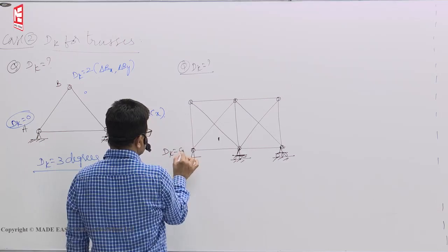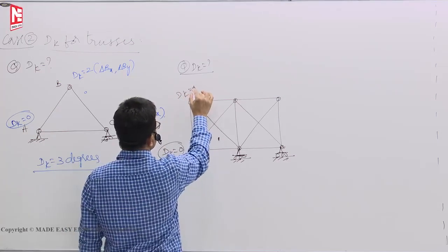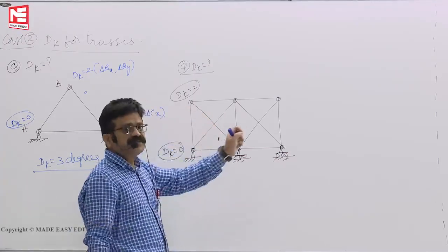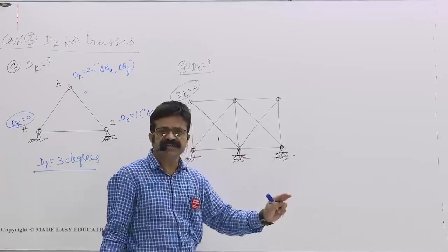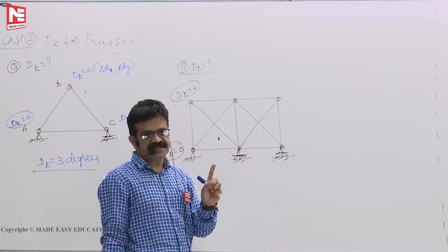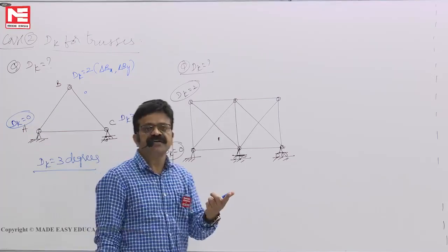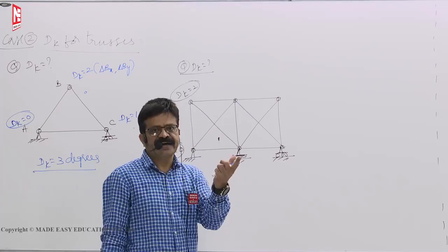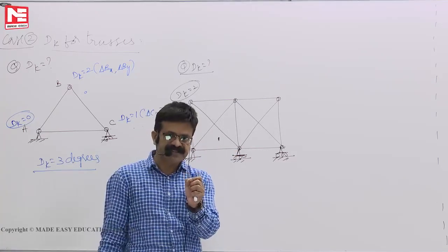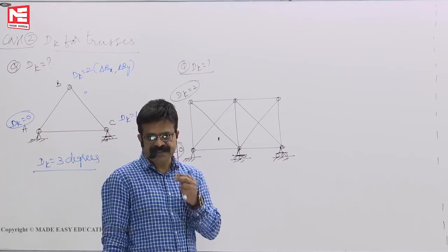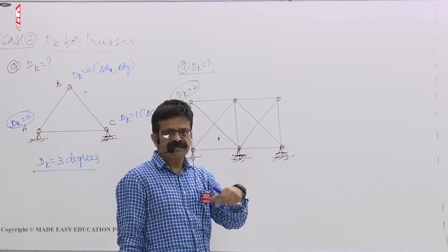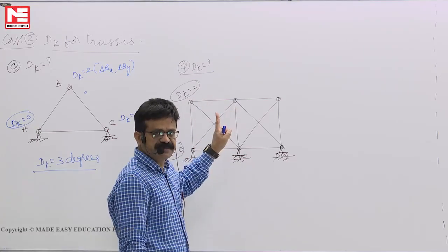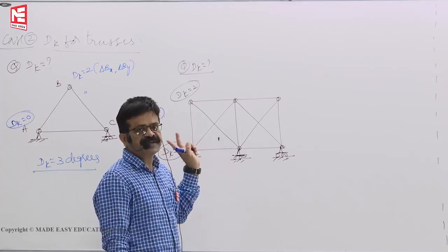Here dk is 0 because it is a hinge support, here dk is 2. Whether counter bracing is there or not, they may reduce the deformation, means translation, and reduce the deflections, but they do exist. You can neglect only second order displacements, means delta squared or theta squared, wherever you find in your expressions, they are called second order displacements. Displacement of order 2, means y squared or theta squared terms we can neglect, but single displacements, first order displacements, however small it may be, you cannot neglect.